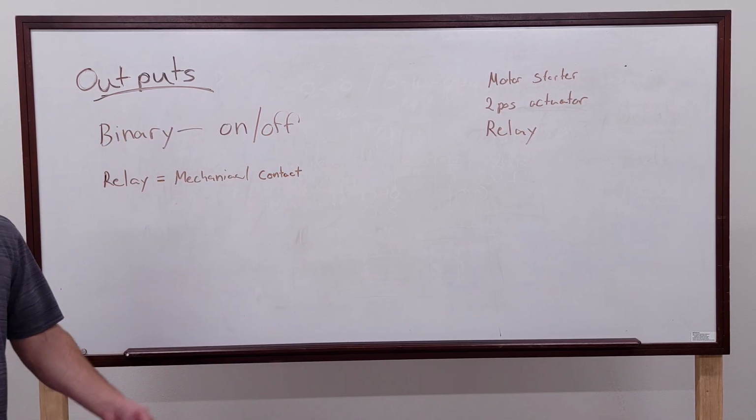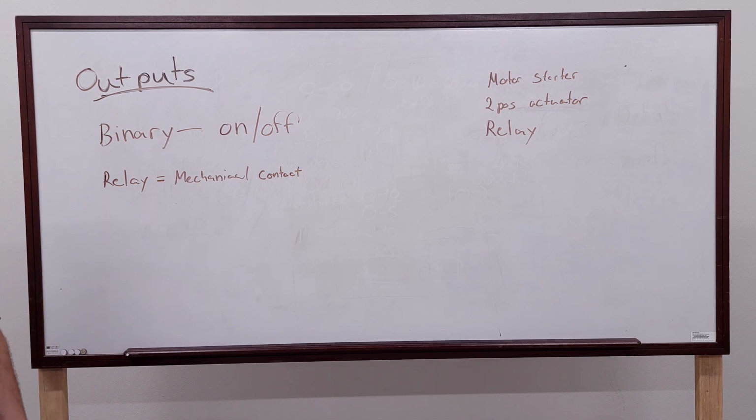So just like a contactor in an air handler, right? It's an actual mechanical contact closing. So inside the controller, it's going to send a signal to these little bitty tiny square blocks on the control board with basically a micro relay in it. And it's going to close a set of contacts and take whatever's coming in and pass it back out.